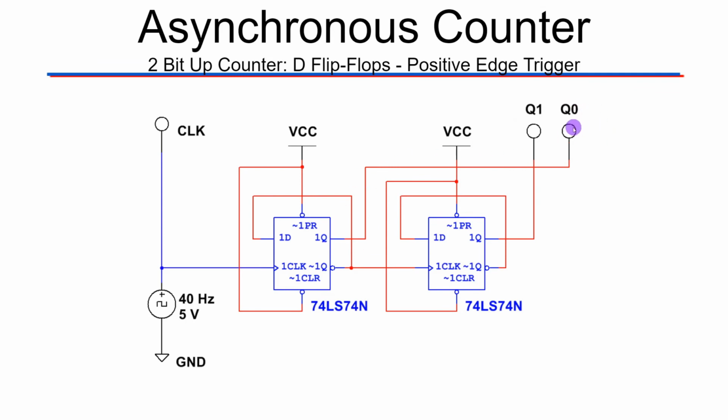Again, the current state of our first flip-flop, and then for ours we'll have 4 bits here, and so we'll be seeing our however many bit binary number represented here. We're also going to add the 7-segment display to double check that so we can see that easier. And then also for ours, because we want to count in a specific range, we're going to add some reset control structure here to actually take advantage of these clears and presets.